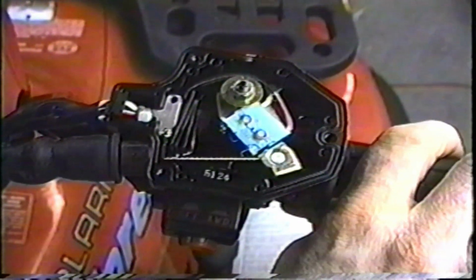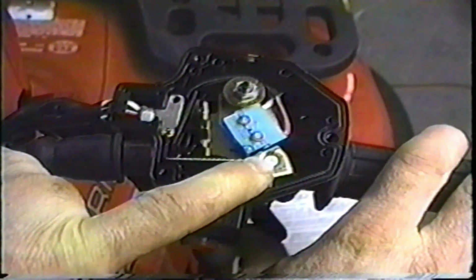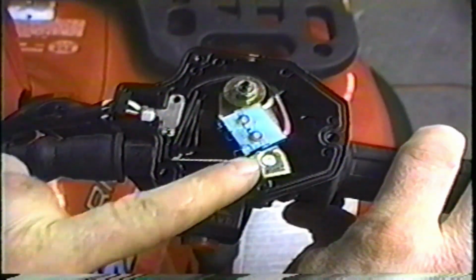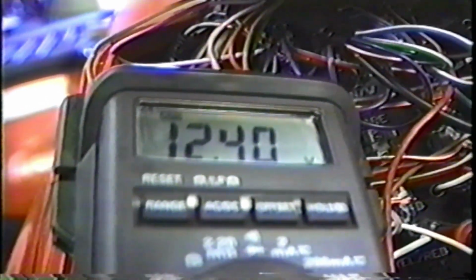The electronic throttle control, or ETC, found on our ATVs is a simple and effective way of limiting RPM in the event of a throttle mechanism malfunction. A speed limiter module attached to the bulkhead monitors engine RPM through a yellow or yellow-red wire from the AC generator's charge coil. When the ETC switch provides voltage to the speed limiter through the white wire, the module shorts the black CDI wire to ground, limiting RPM. When RPM falls below a predetermined ETC limit, the speed limiter module no longer limits RPM.